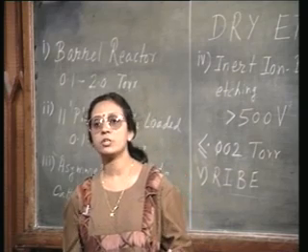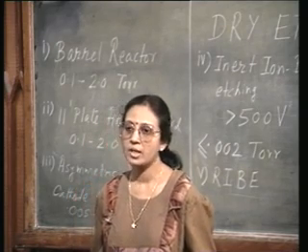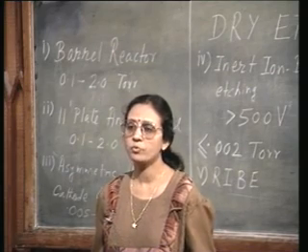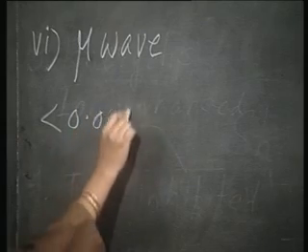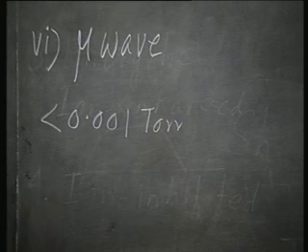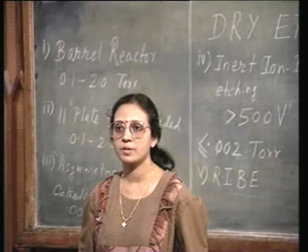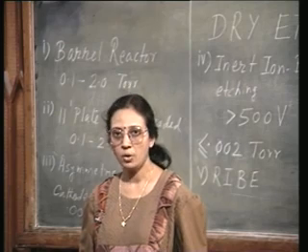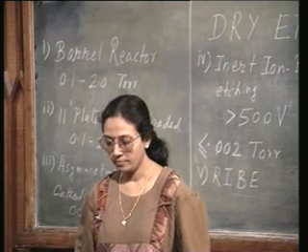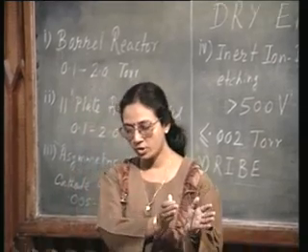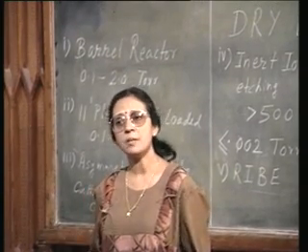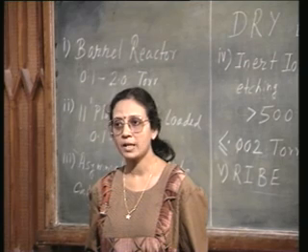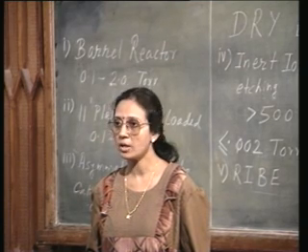So, usually of course, because the sheath potential is very low, you will have isotropic etching, but if you go to very low pressure, less than 0.001 torr, then you can get some anisotropy. And another variation of this microwave plasma reactor is called a downstream reactor, where you have two zones. Plasma is confined in a remote chamber and the wafers are held in another chamber. So, then again you have some directionality. Anisotropy can be improved.